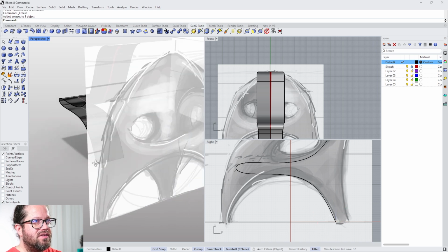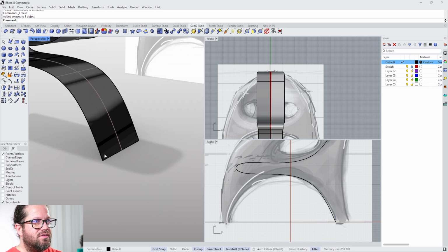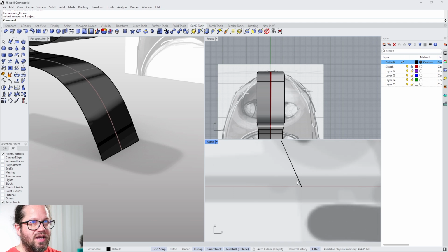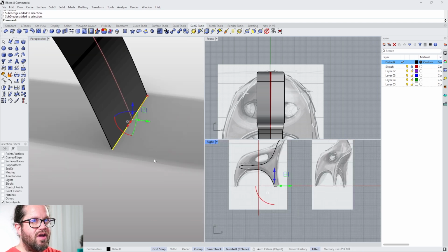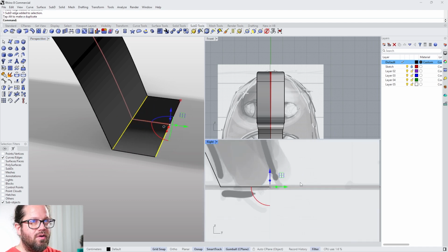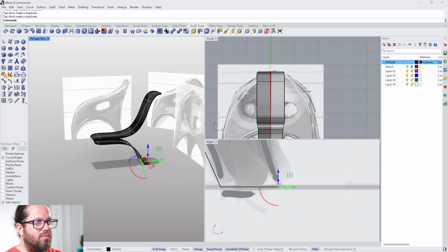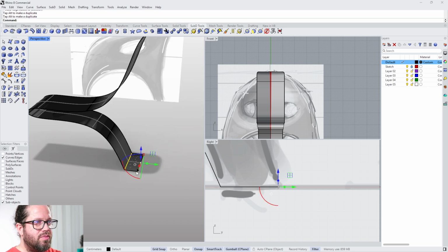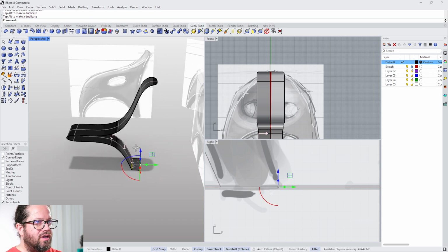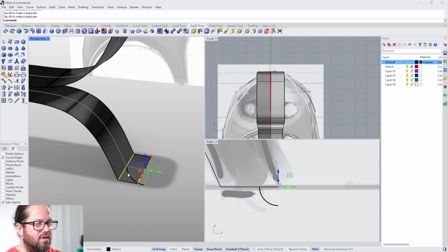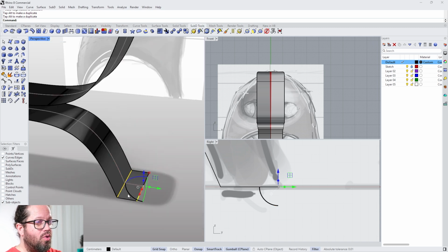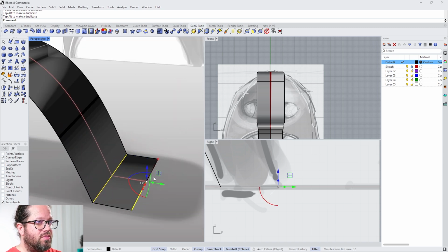And now this has snapped down to the floor because that's where we pushed it before. We pushed it exactly here. If I now select my edge and I want to extrude it again, you see it stays flat. That's exactly what we want in that case. There are, by the way, other ways to model these hard edges by creating a bevel or creating additional edge loops which get pushed to the corner, and that makes it a more realistic version. But in this video we'll just use this method.